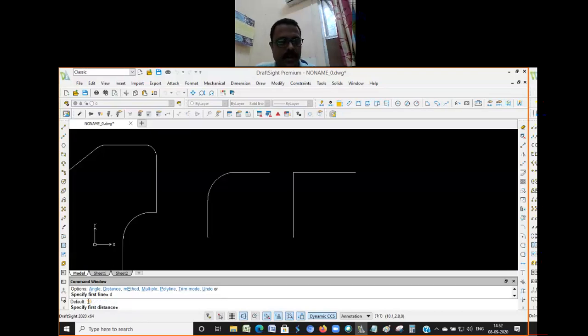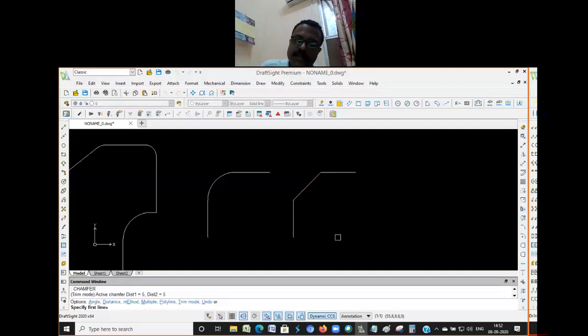So the distance by default is 10 millimeter. I use 5 millimeter on both sides. Okay, this is my first line, this is my second line. So you see the difference? Yes, sir. So basically, if you use chamfer, you don't get a round shape or a smooth corner.